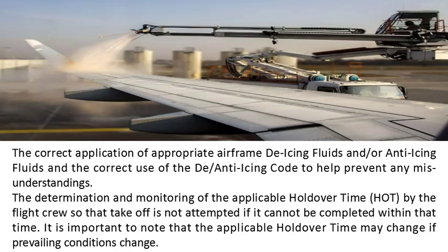The correct application of appropriate airframe de-icing fluids and/or anti-icing fluids and the correct use of the anti-icing code to help prevent any misunderstandings. The determination and monitoring of the applicable hold over time, HOT, by the flight crew so that takeoff is not attempted if it cannot be completed within that time. It is important to note that the applicable hold over time may change if prevailing conditions change.